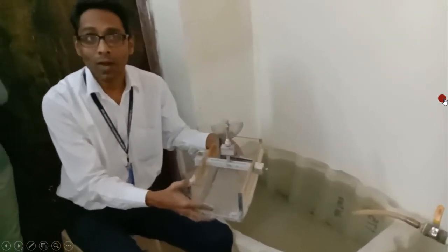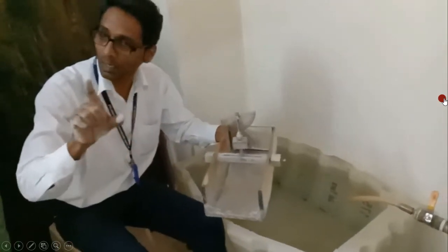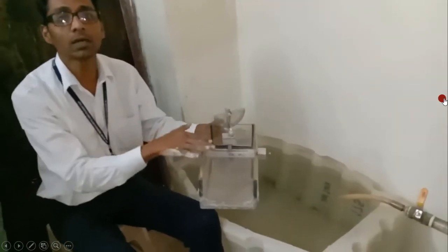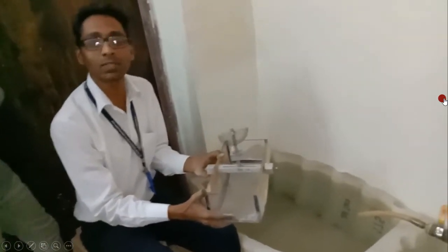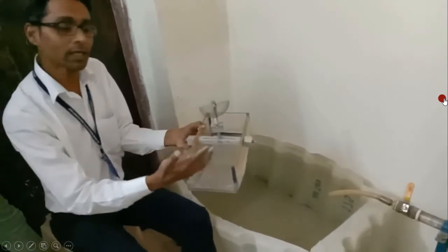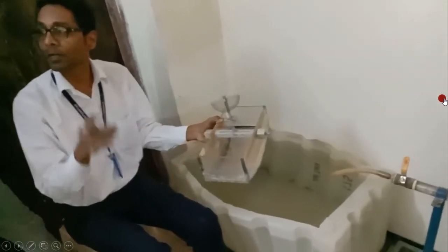Why? For validation purposes. Validation means that the metacentric height we have obtained by the analytical method is compared with the value obtained by the experimental method. If these two values come near, then we say it is validated. Validation means confirmed. So in ship manufacturing, the experimental method is used after the manufacturing, and the analytical method is used before the manufacturing to obtain the metacentric height.